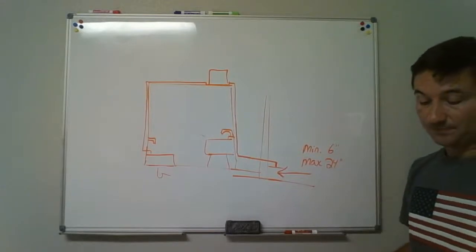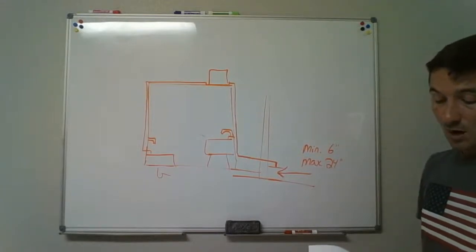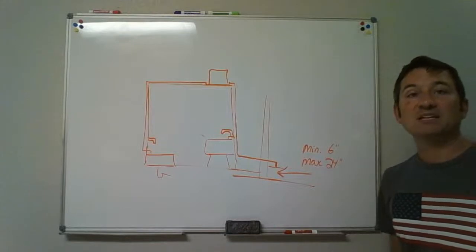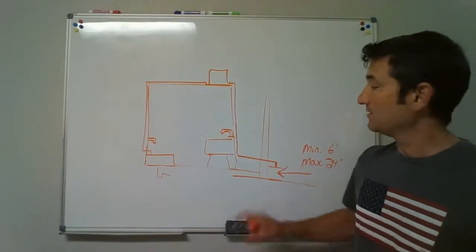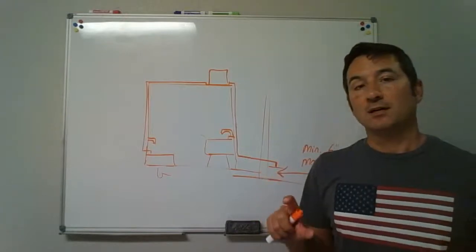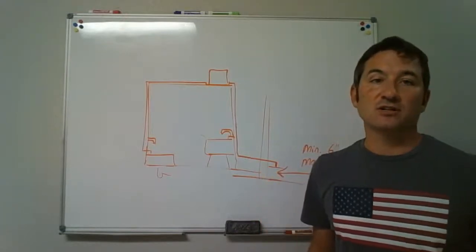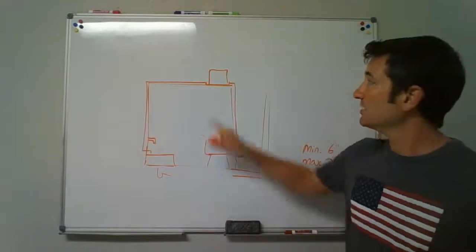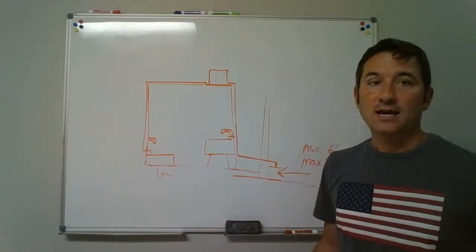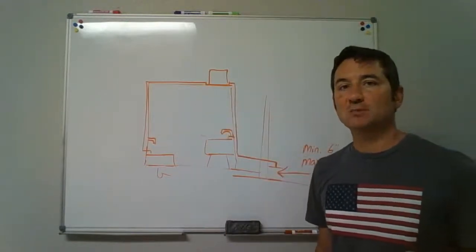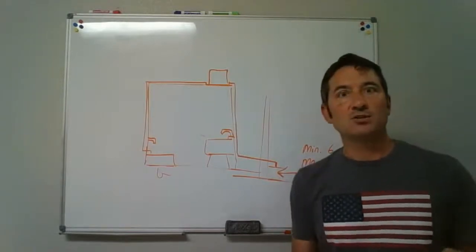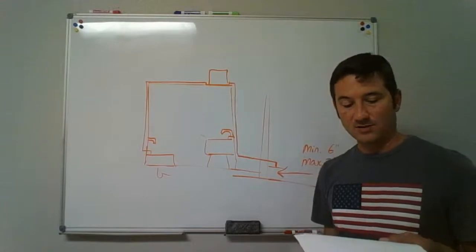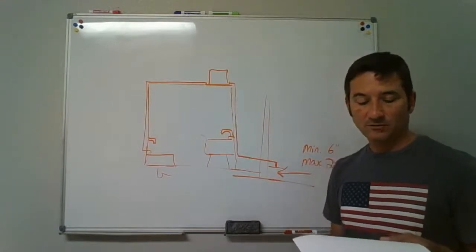And number 7, a water heater pan must be at least 2 inches deep. Now, I'm not asking about the base that the water heater sits on. We said that has to be at least 2 inches, but the pan for the water heater, was that at least 2 inches deep? Was that true or false? Or was it something else? Maybe an inch and a half? I believe that's what we said. So 2 inches would be false.